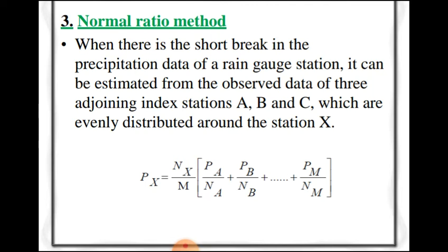If the data is consistent, typically it will follow a straight line with minor variations. But if there are changes in the characteristics of the catchment, or the gauge has been shifted, causing some inconsistency, then the data does not follow a single straight line and deviates from that position.